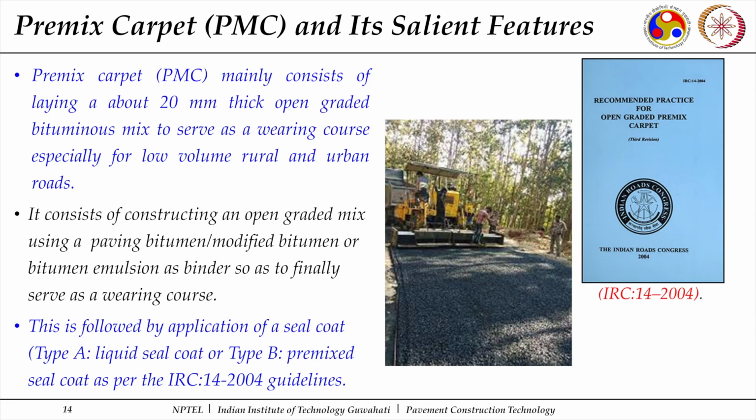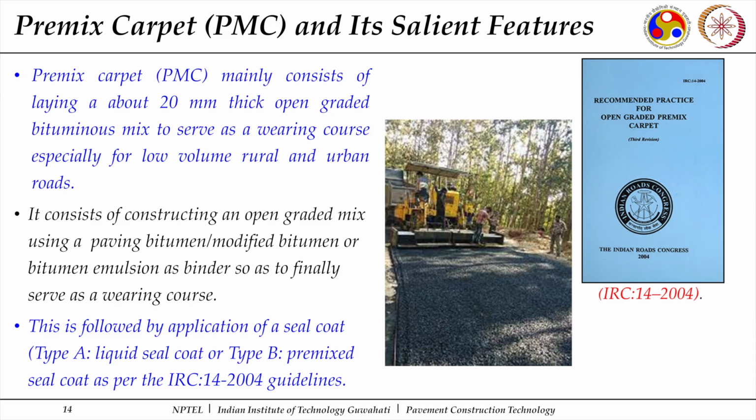Now different types of binders are used. Most probably the ones preferred are either paving grade binder, which needs to be heated before applying, or bituminous emulsion, which doesn't require heating, so it can be applied at ambient temperatures. Later on, during bituminous mix design, we will discuss the different types of binder: what is a bitumen emulsion, what is a paving grade binder, and what is a modified binder. At this moment this is good enough.